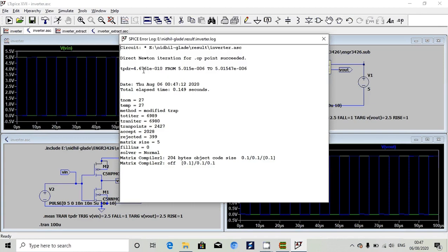This is the result we are getting only by using our model file, but we are getting 640 picosecond as the new delay after the post layout simulation. We are gathering the information from layout, so it is including some of the parasitic capacitance into effect. So we are getting 640 picosecond as propagation delay, but without that we are getting 467 picosecond.